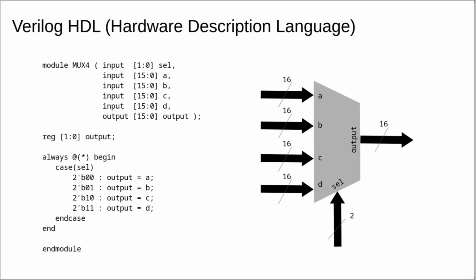So here is a very short introduction to Verilog HDL, HDL standing for Hardware Description Language. This is not going to be an extensive tutorial. In any case, there are awesome videos available on YouTube. I advise you, if you are interested, to have a look at them. Verilog is a programming language that describes hardware. So what we're doing in the language is we are writing a program that is going to result in hardware. It can be synthesized to hardware.